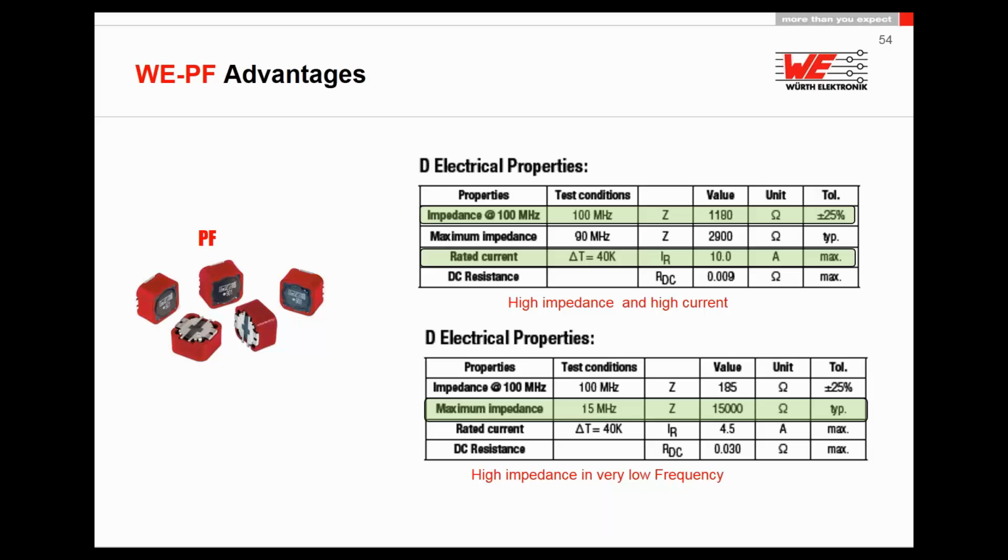They are bigger, of course, and do not fit the small sizes. You will not find them in 0603 size, but they can withstand a much larger current, and they also have very low DC resistance. And if you apply such a big pulse that you kill the coils inside this copper wire, then you don't talk anymore about normal designs or standard EMC or standard load dump.